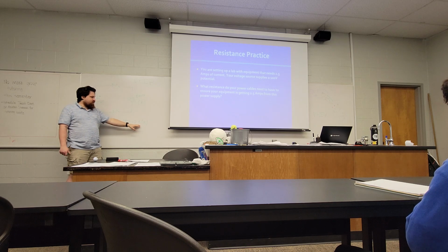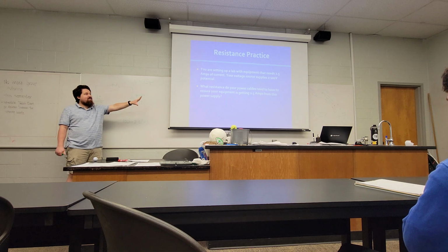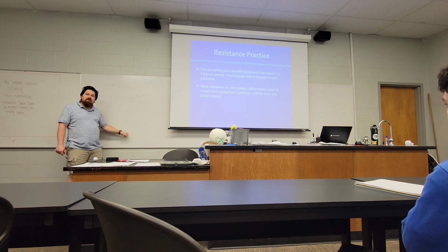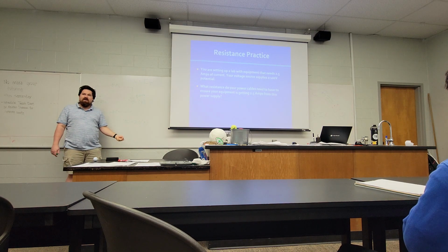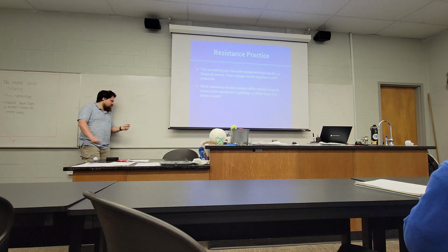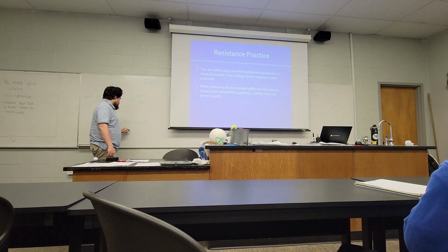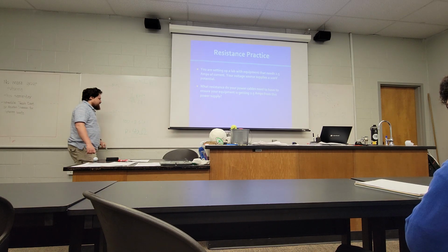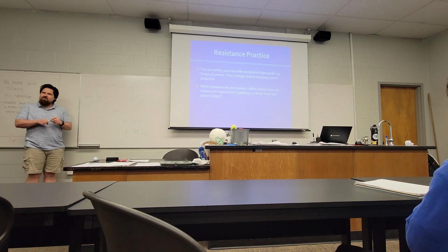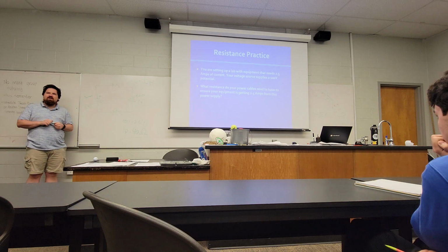Any device cranks up the resistance of your circuit. In this case, what we're doing is calculating the maximum amount of resistance that we can have in this situation to make sure we're getting that 2.5 amps. So we divide by 2.5 and we do get the 40 ohms as said. The symbol for ohms is the Greek letter omega, by the way.